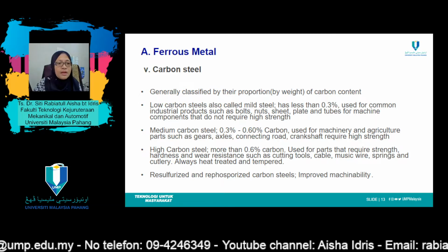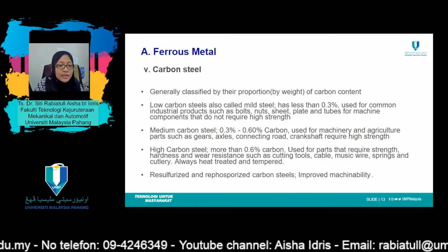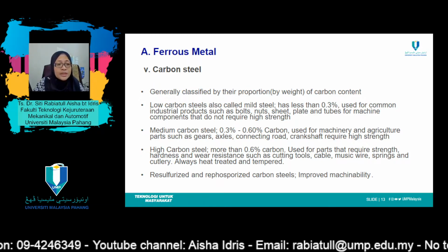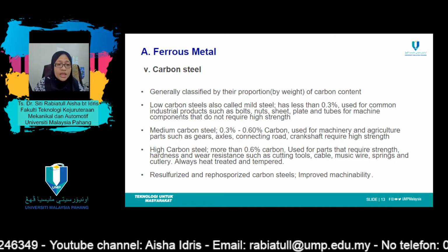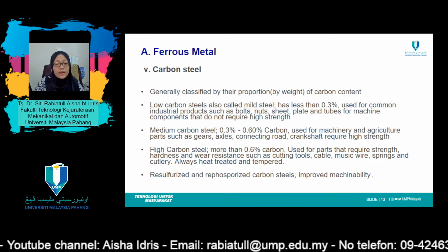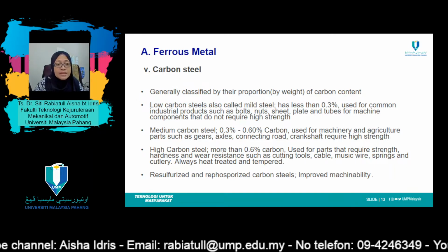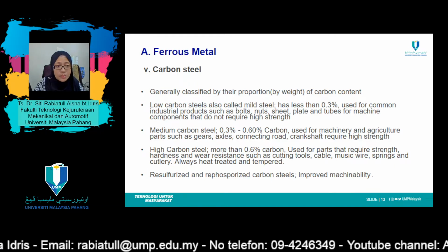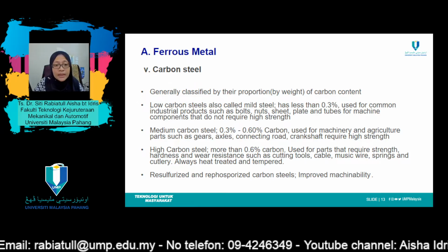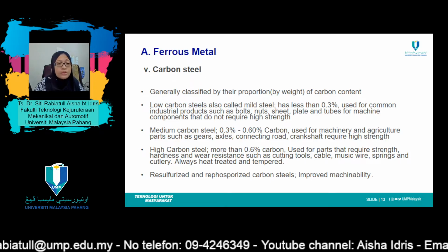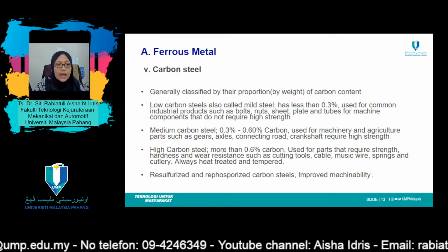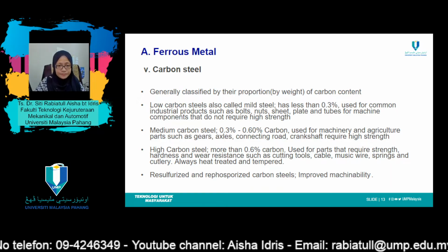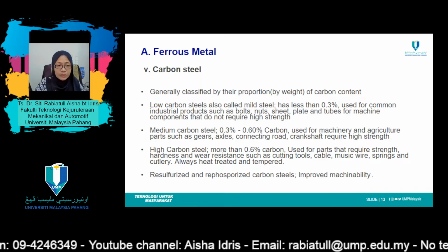Some of the common steels are classified according to carbon concentration, like low, medium, and high carbon steel. Subclasses also exist within each group according to the concentration of other alloying elements. Plain carbon steel contains only residual concentrations of impurities other than carbon and a little manganese. For alloy steels, more alloying elements are intentionally added in specific concentrations. Now let's look at them one by one.